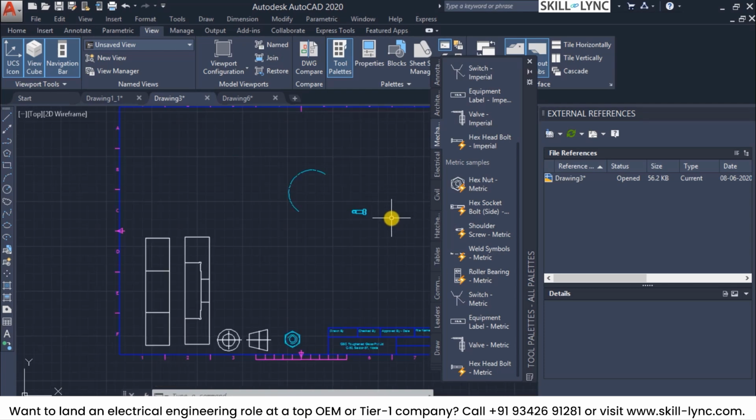So this tool palette we can use to configure several geometric objects that we have seen, like the lines, circles, arcs, polylines, and then we can also create dimensions, blocks, hatches, solid fills, gradient fills, raster images or external references. So it means that you are using a quick access panel wherein you are keeping reference of all the frequently used things. For example, you can create any custom object with a fixed line type and a line reference, and then store it in here. So whenever you're using it, the same thing can be applied.